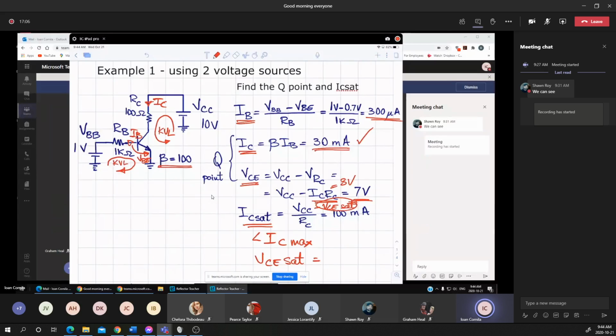But if I'm comparing 0.1, 0.2 with the VCC, I can neglect the saturation voltage, which means I'll make the saturation voltage almost 0 volts. That's why, to simplify our calculations, I'm assuming that the VCE saturation is 0 volts, and it's not part of the equation. But strictly, if we have to make the precise calculation, I'm choosing the VCC minus the VCE saturation as 0.2. Again, in our applications, I'm choosing the VCE saturation as 0 volts.